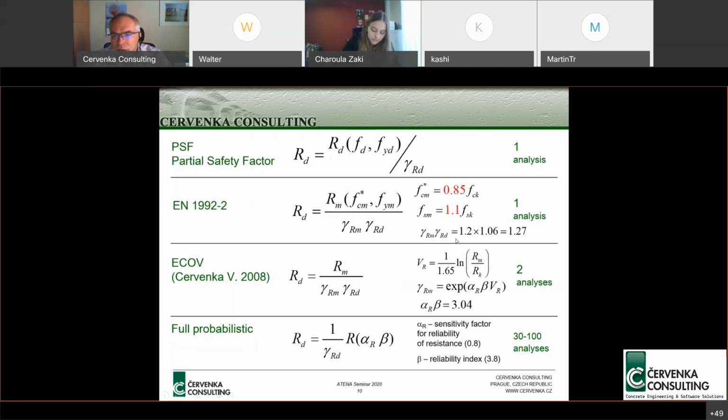Well, then the second approach here, I'm just describing it for reference, because in the Eurocode for bridges, there is already nowadays some safety format which suggests to make kind of an average, to estimate the average strength by using modified material properties for concrete and for steel, which somehow represent uncertainty of these two materials.